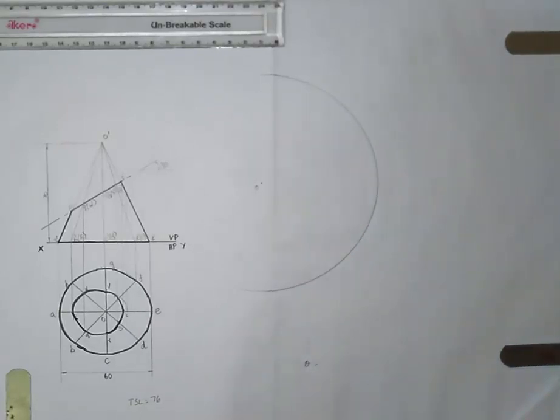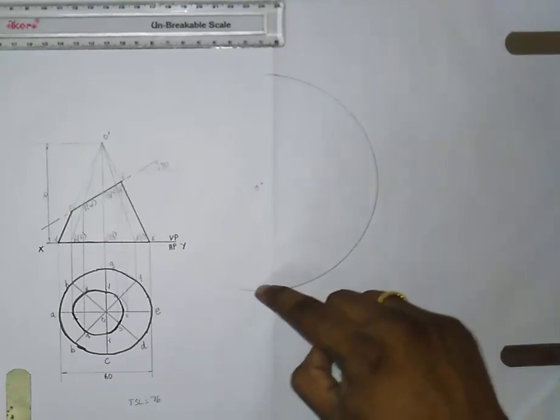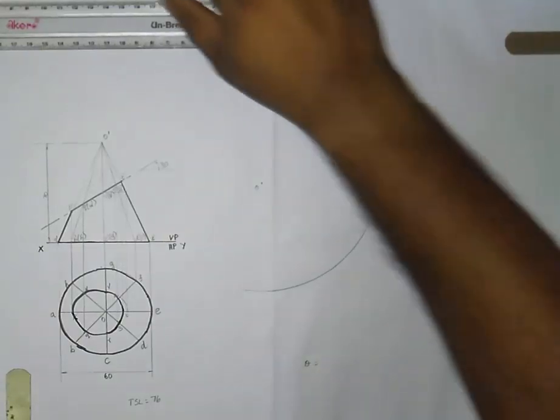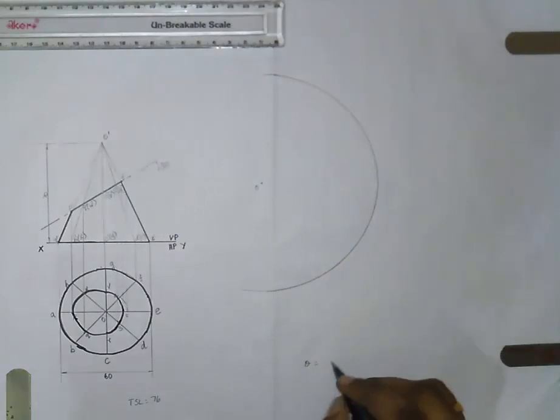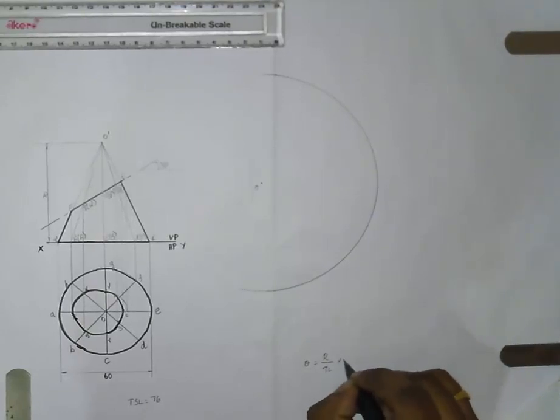Now in the bottom base, when you open the cone, you will not have straight lines, you will have a curved line. So this curved line length must be found in order to draw the development view. There is a formula for that. The formula is R divided by true length, into 360.